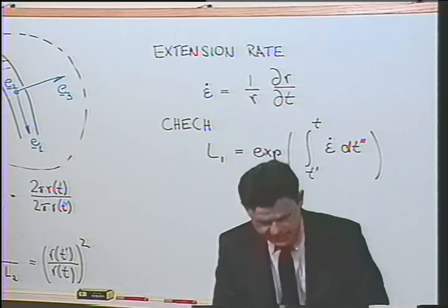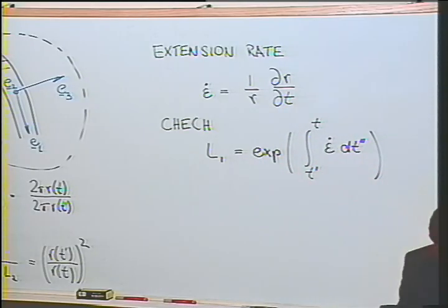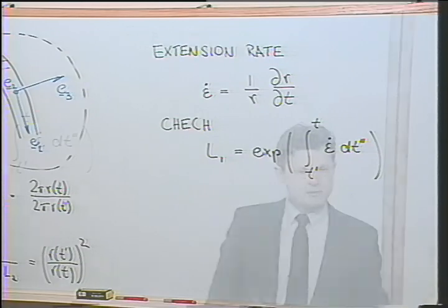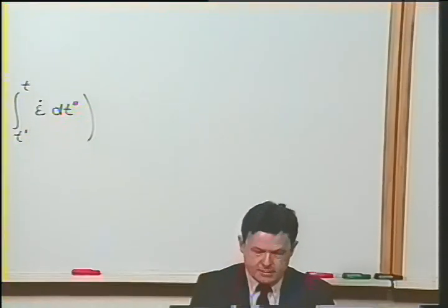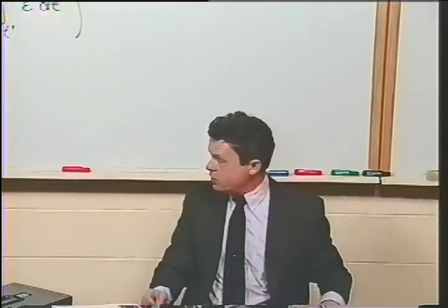With this result, we can now go to the strain tensors which we calculated before, which we calculated in class. The flow associated with blowing up of a balloon is extensional flow. In this case, it's biaxial extension because we're stretching in one direction and equally in the 2 direction, and it's shrinking in the 3rd direction. So that type of flow is a biaxial extension.